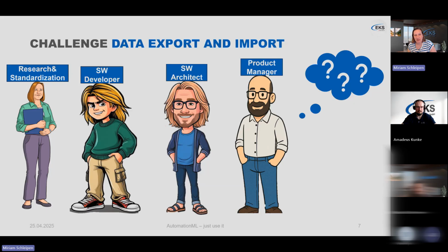Like, for example, if you want to exchange the information from an electrical planning to a PLC programming tool. There is already a lot of domain-specific knowledge defined in AutomationML, but there are also parts like our process description, the analysis, different process steps, where you do not really have a standardized solution, but you have the possibility to use the mechanisms in the standards, what I would call meta modeling possibilities.